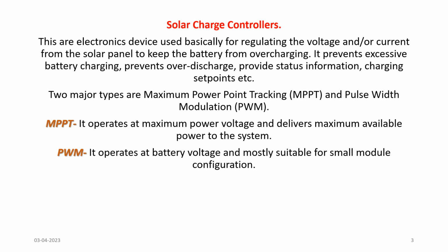For the PWM, we operate at battery voltage, and you will see in some literature they say it will charge a little bit above the battery voltage, and this is not that efficient. So that's why some people choose MPPT over the PWM. And this first picture is the PWM type. You can see the panel comes in first, the battery, and the load. The load is not really mostly useful,